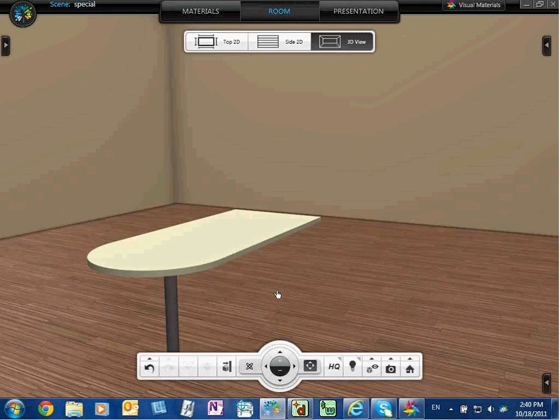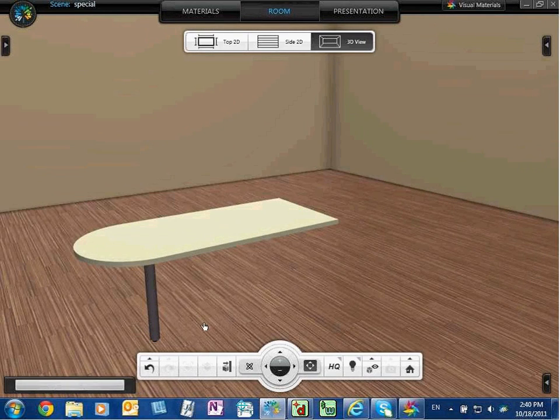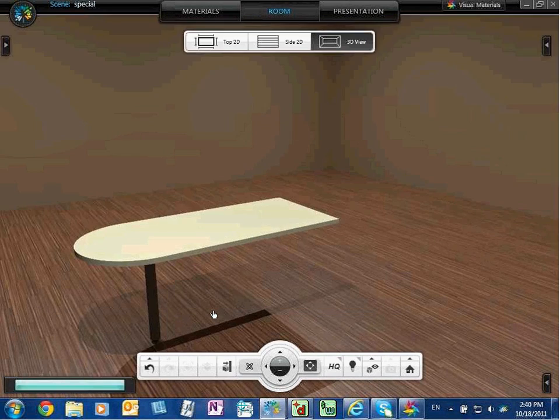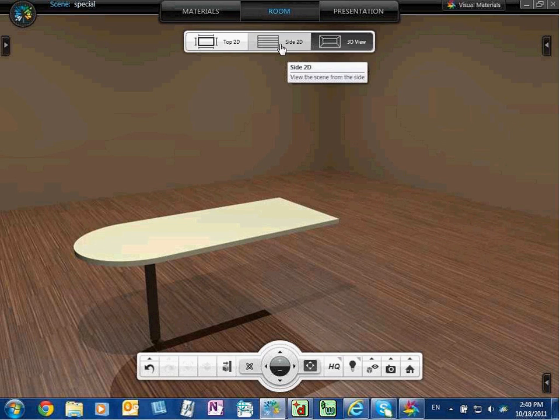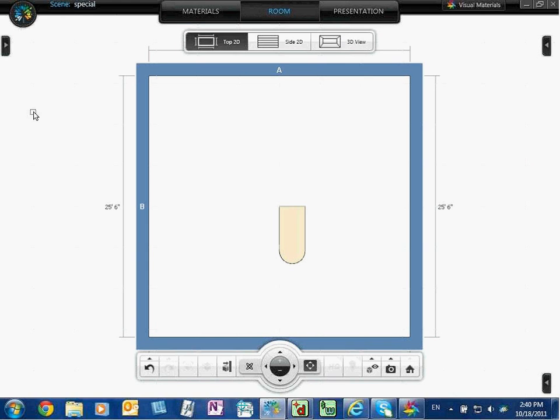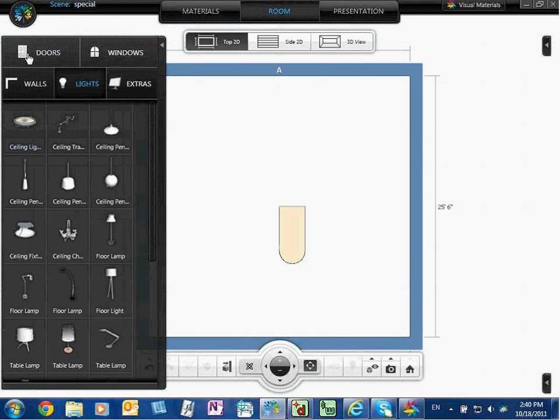Okay, on lighting, but I have a user that's been on hold here due to the new questions coming up. What's the best way to change the window heights and visual impressions so they are all the same height? Well, the best way, the only way to change them right now is to go into your room setting and let me put a window here real quick.